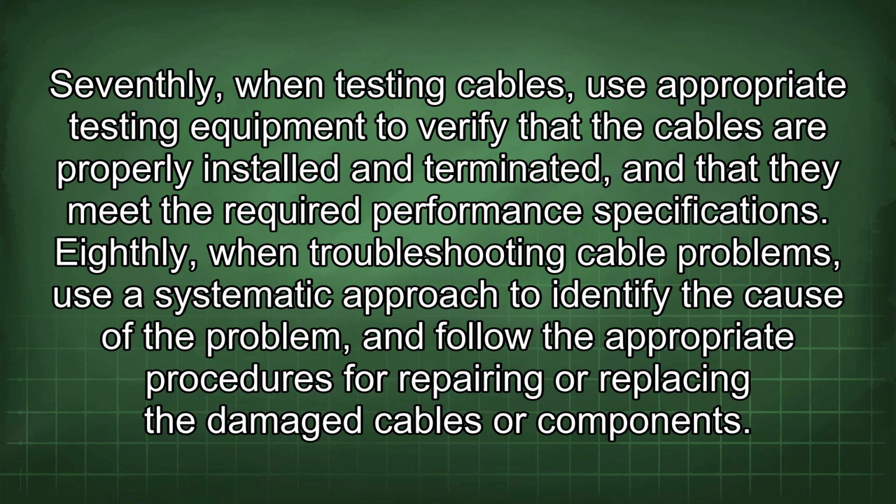Seventhly, when testing cables, use appropriate testing equipment to verify that the cables are properly installed and terminated, and that they meet the required performance specifications. Eighthly, when troubleshooting cable problems, use a systematic approach to identify the cause of the problem, and follow the appropriate procedures for repairing or replacing the damaged cables or components.